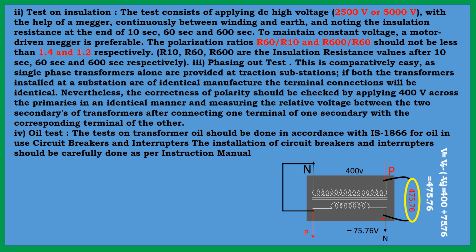And the oil BDV value is also an important test, to check how far it can withstand, and whether moisture is present in it or not. It is measured in kilovolts, as breakdown voltage. It is called breakdown voltage. It is the voltage at which the oil breaks down or is punctured, allowing electric current to flow between the two terminals where the voltage has been applied.